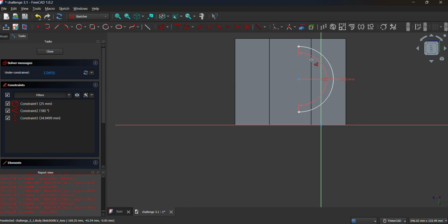Again, the edge is not clickable, so let's create an external geometry by clicking this tool and then make sure it turned purple. Since that is already purple, and later we will also be using this external side, let's prepare and click add external geometry there. From the center to here, as I have mentioned repeatedly, that is 40 millimeters.